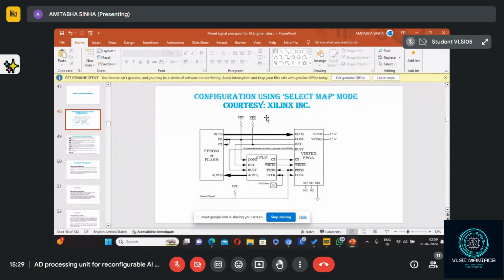So when the CPU gives the information, the download means you program the FPGA. Along with that, it must send two sets of information. One is the start address of the bit streams, and second is how many bytes are to be transferred. That is called the byte count. Each time one byte is transferred, the byte count becomes the previous value minus 1. This process continues until the byte count goes to 0. That is the process of programming.